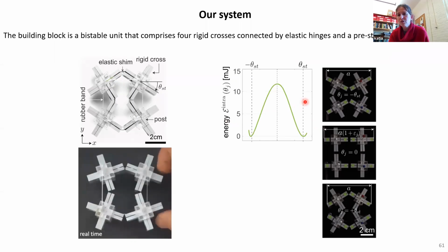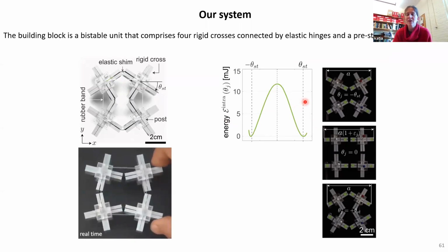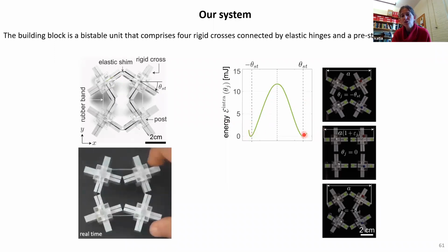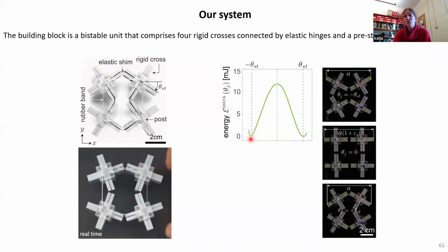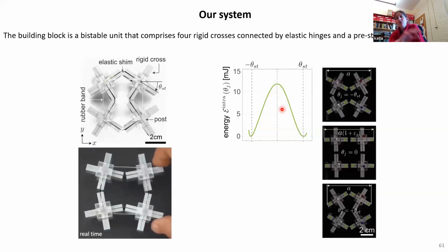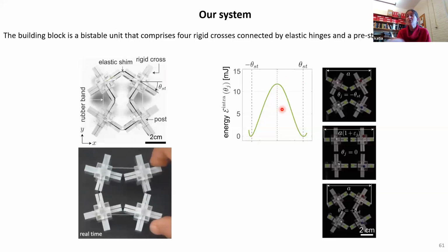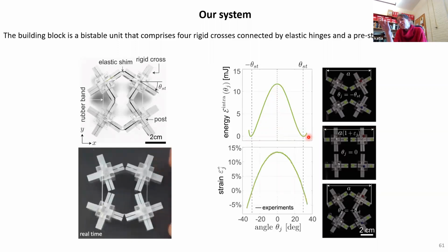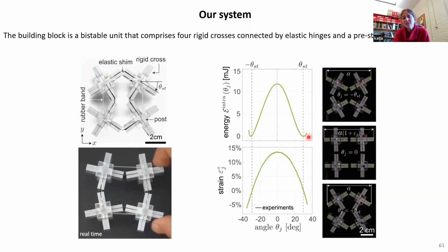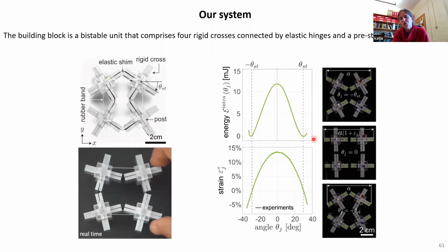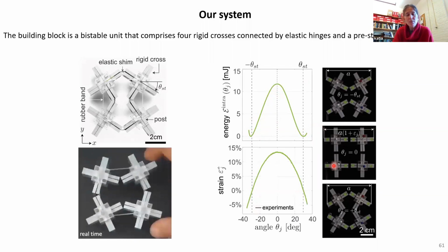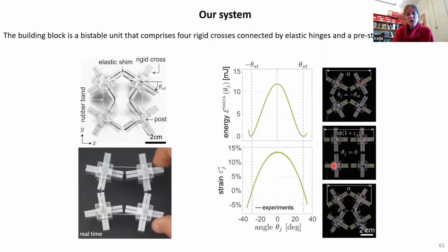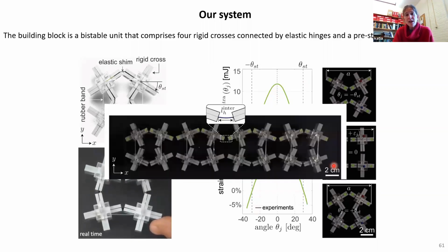By integrating the force from a uniaxial test, we can obtain the energy. What we see is that the structure has two stable configurations, corresponding to the two rotated phases, separated by an energy barrier. In this case, the profile is symmetric, right? The two energy wells are at exactly the same level. Also, as the structure transitions from one stable configuration to the other, it elongates and then it shortens. All right, so now we have our bistable unit cell.